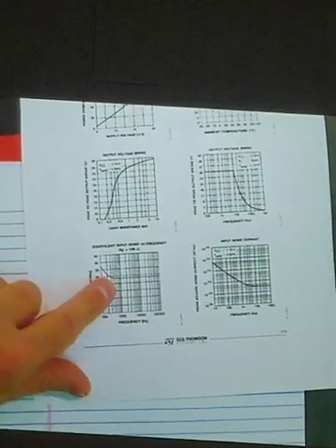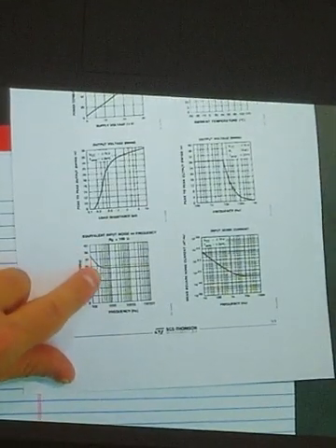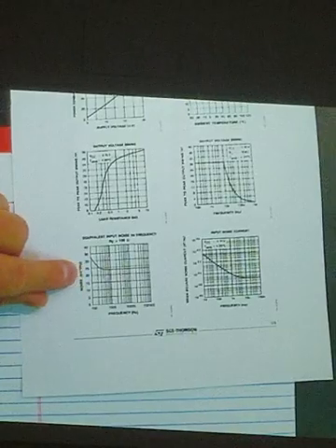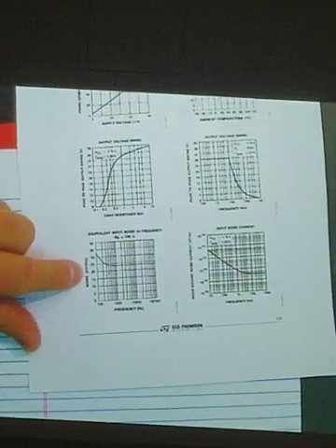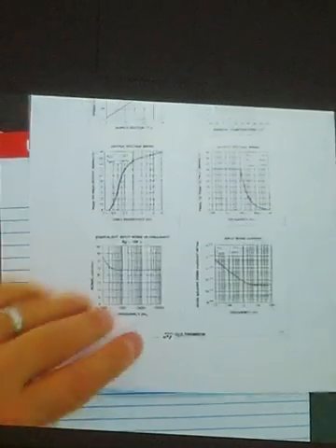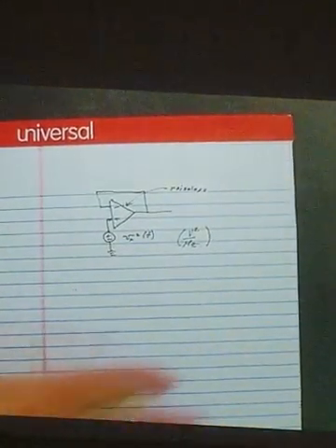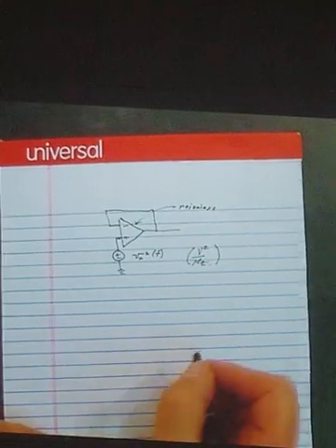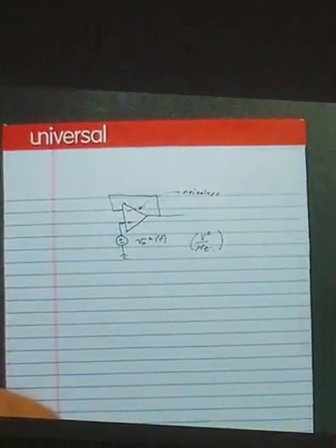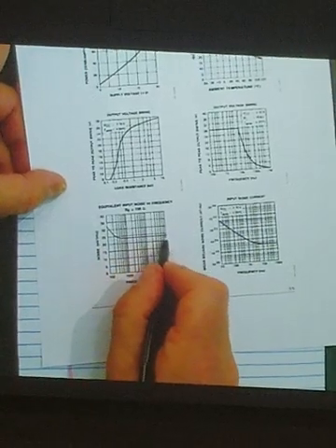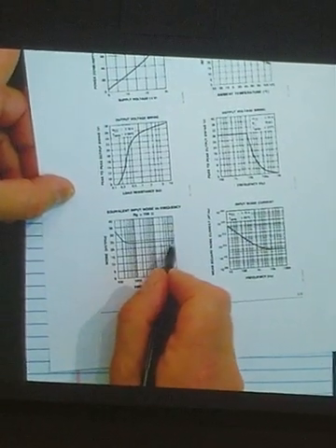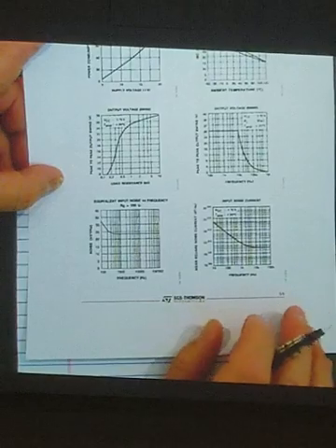And forget for the moment that it kicked up here in the end. If you can't read that, that line is just below 25 nanovolt per root hertz. So we'll call it 25 nanovolt per root hertz. So the power spectral density of this noise is 25, actually that's the square root of the power spectral density.